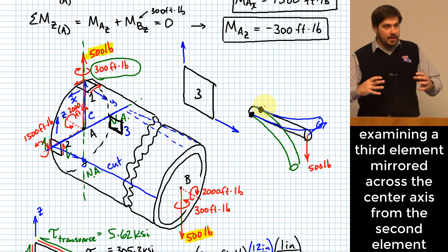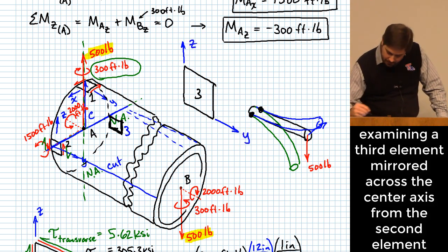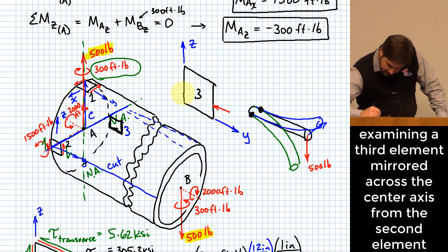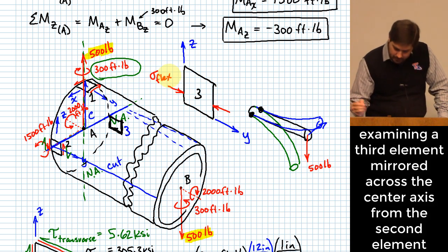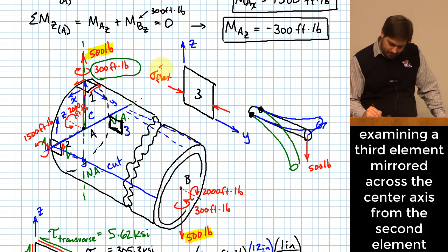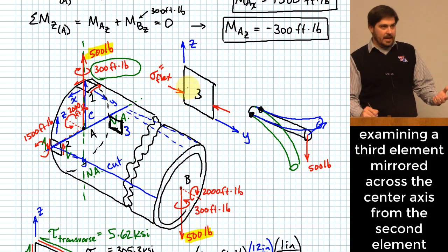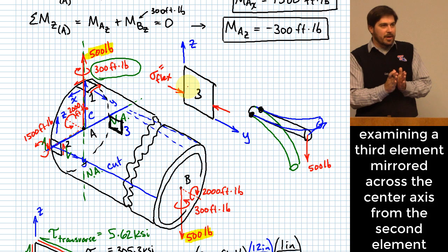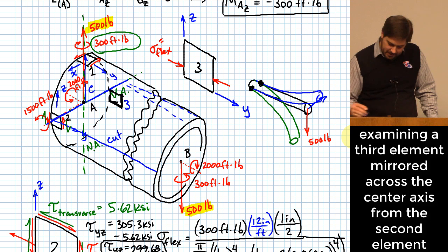Compressing. Okay, so in that y direction, where that's the z direction, we would have a compressive stress due to flexure, right? Would it have a different value than we had before? No, so this would be what? Okay, this gets a little bit tricky. Since I drew the arrows inward, I don't put a negative value, right? So relative to the direction I showed my arrows, I say that this is still a 91.6 KSI.